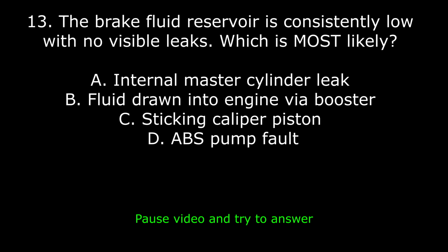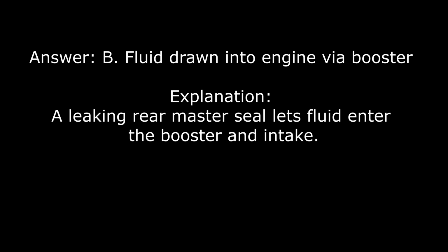13. The brake fluid reservoir is consistently low with no visible leaks. Which is most likely? A. Internal master cylinder leak. B. Fluid drawn into engine via booster. C. Sticking caliper piston. D. ABS pump fault. Answer: B. Fluid drawn into engine via booster. Explanation: a leaking rear master seal lets fluid enter the booster.